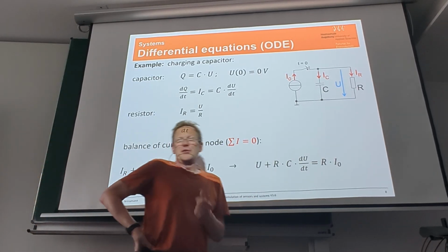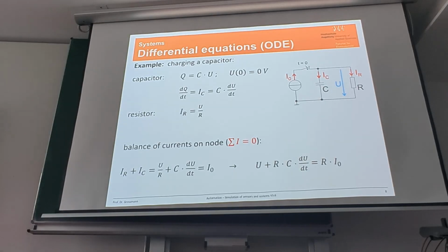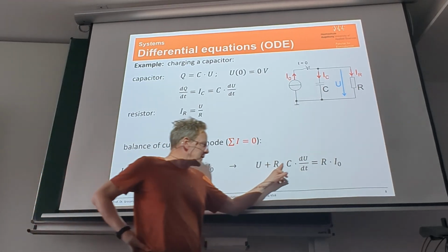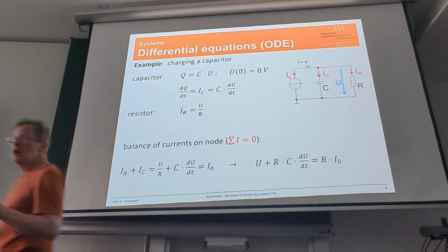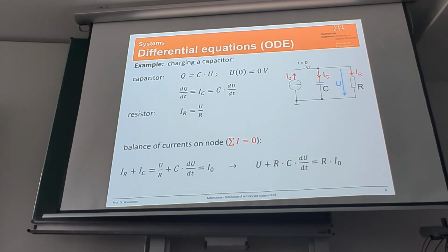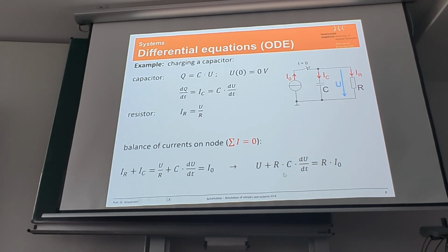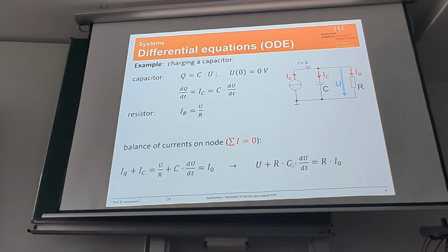For a capacity, it's farad, but farads, well, what is that again in SI units? But no, we don't have to know it. It's not necessary. R times C is nothing else than our constant tau from the last page. And we said this must be a time, because here we have voltages divided by seconds. We want to add this to simply volts, so we must first multiply this with the seconds. So R times C must have the unit seconds.